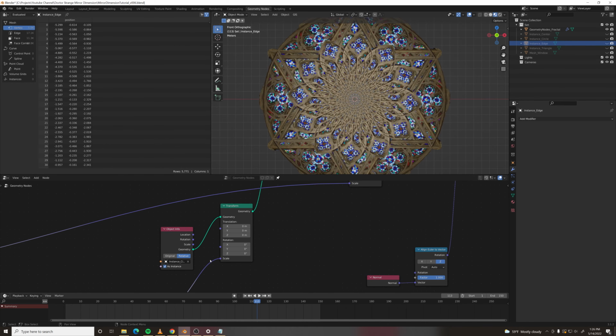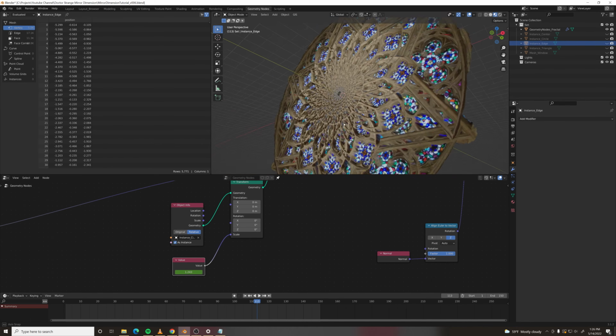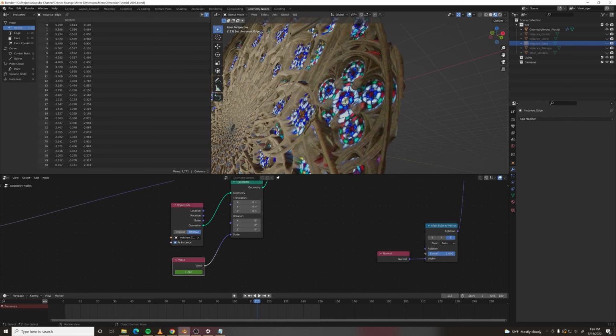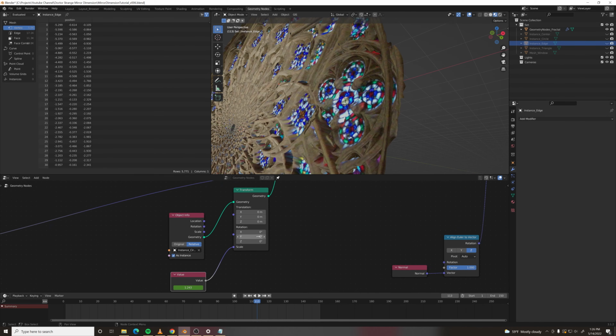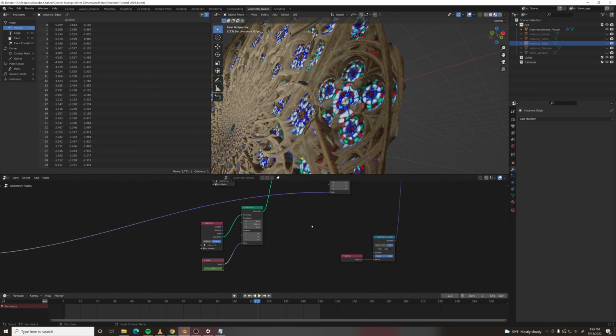One thing we want to do is move this circle so it's slightly underneath the other mesh, because we don't want faces that perfectly overlap. So if you move it down on the y-axis just a tad, 0.02, then they won't overlap.